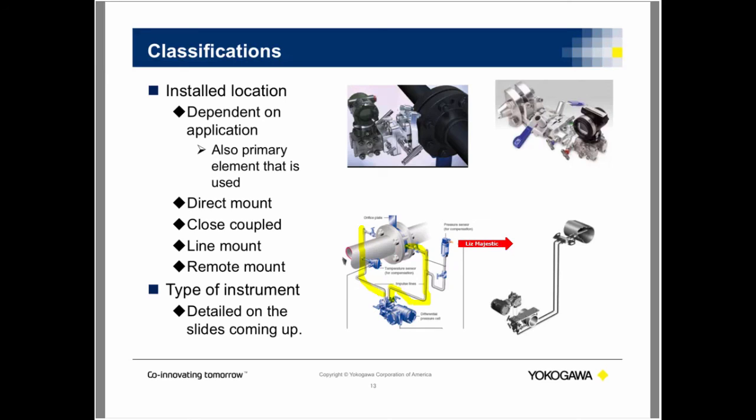The transmitter is generally mounted at grade, but it allows you to get away from the process. So it allows your manifold and your transmitter to be away from any type of spillage or temperature, so that your technician can get to your manifold and your transmitter easily and it can be easily serviced. That's why it's extremely popular.